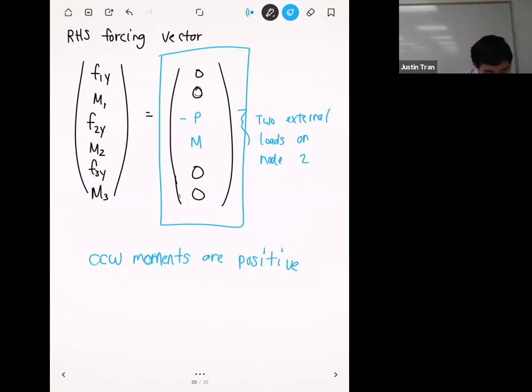Okay. All right, and so that's the basics of beam equations. Again, the process of solving all these problems, maybe you're getting sick of them at this point, but the process is all the same. The only big difference between all the different methods is what you plug in for the element stiffness matrix. And so the beam has its own element stiffness matrix, but once you get used to using that, then the whole problem solving process is the same. It's lengthy, but at least it's the same.